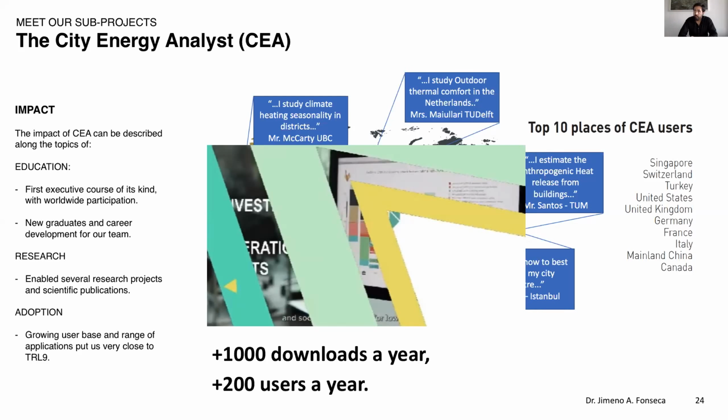For the framework that we developed and that you can download, there have been already a couple of projects which have explored the aspect of calibration. Some of them using what we call the Bayes theorem of calibration, which doesn't provide you one single endpoint estimate, but more of an entire probability curve of where your parameter is more likely to be according to measured data, as well as other approaches just looking at a grid search of the multiple combinations and understanding which is the one that fits your data the most. So these approaches, you can find them in the legacy folder of CEA. It's part of the research projects that many people have contributed to over the years.